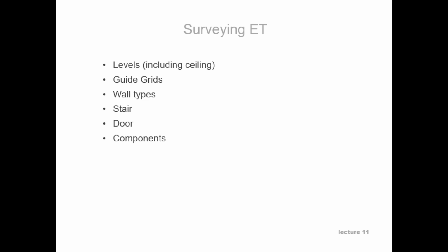Before surveying, I like to have a quick sketch of what it is that I'm trying to obtain measurements of first, even if my sketch isn't perfect. It allows me to have a connection between observing, drafting, drawing, and comparing it to the final building. And then I can begin the technique of measuring every wall length and opening. We're going to give ourselves the same sort of grid guides when we get back into Revit.